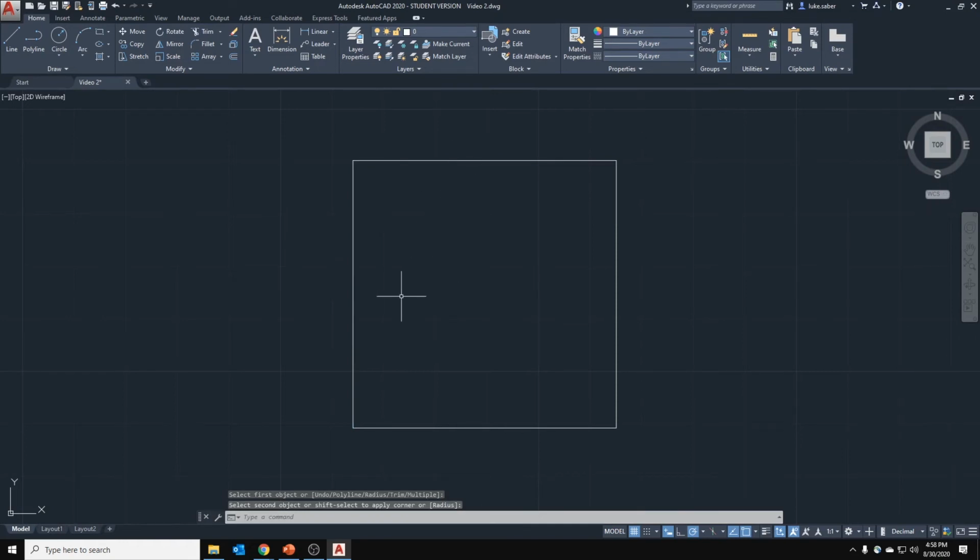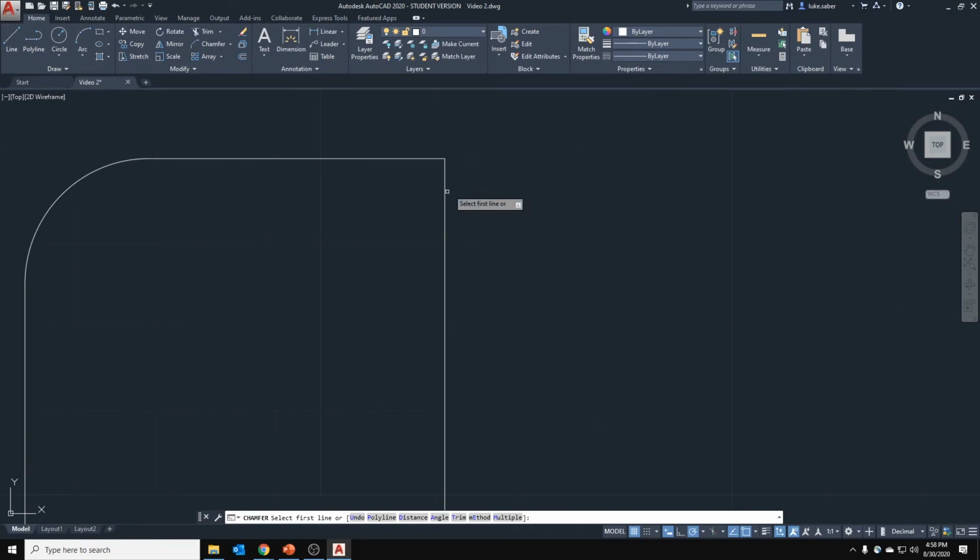That's pretty crazy to be honest, but if you take a look at the difference here, now I'm just doing Control Z and Control Y to go undo and redo. Basically, from a corner, what it does is it goes in the radius, draws an arc, and then cuts away and trims the rest of it. So it's using tools that are already there. It's just making extra steps. Chamfer is similar to this, but not quite the same.